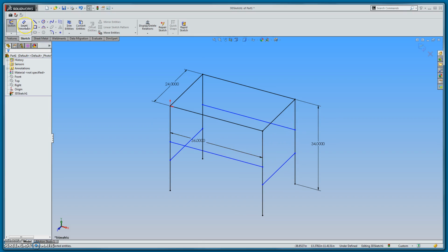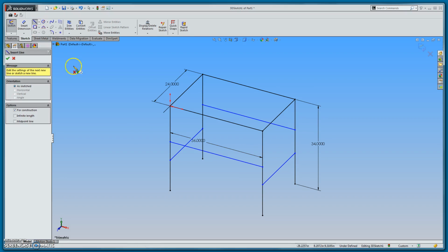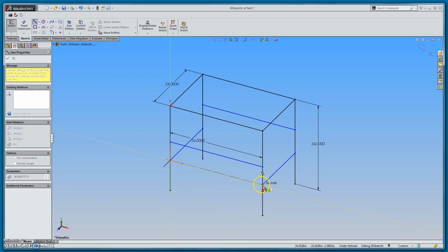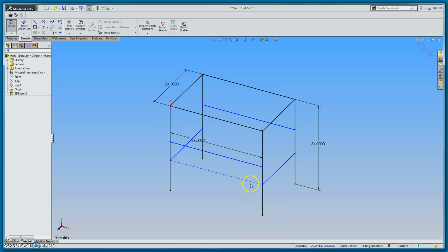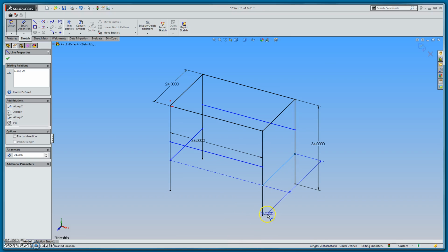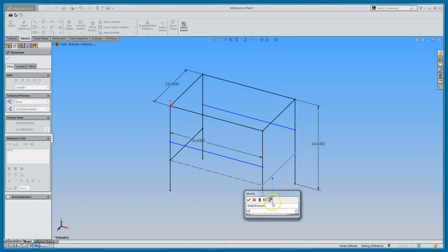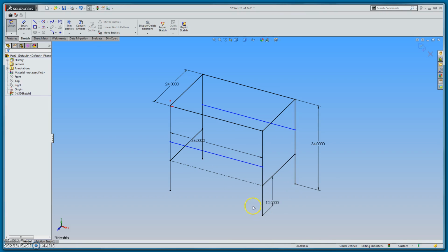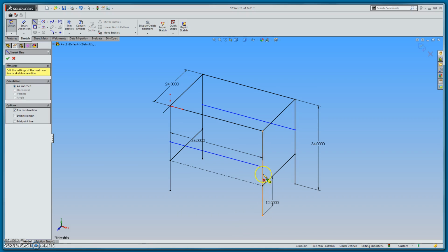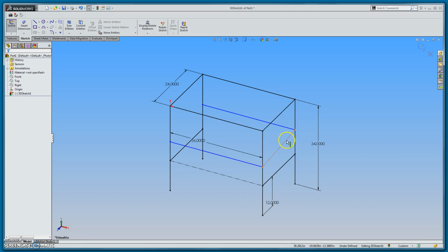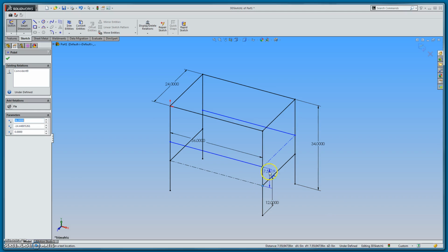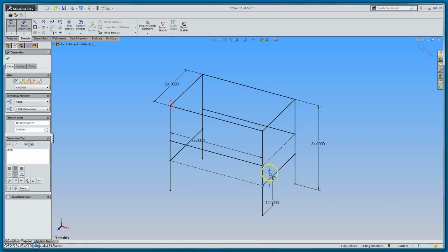And so now what I can do here, I'll use a construction line to make these two same. Make that along dx. And we'll bring those up 12. These are going to be my cross members. And we'll do the same going across these. These will be a little bit higher up. Just some under supports for this table Z. And how about 8 inches above that? Really doesn't matter.